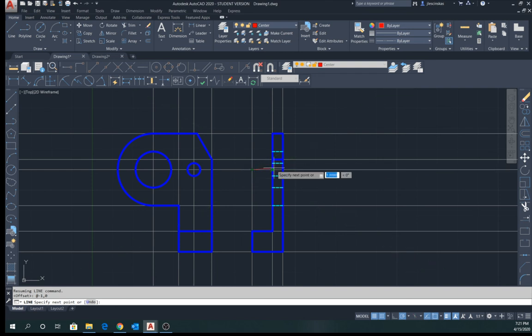And because I know that we're 1 inch away here, this is 0.5 inches wide, I should make this 2.5 inches long, and that will snap it exactly 1 inch from the other side. So that takes care of our center line. I haven't put in center marks yet, and I'm not going to do that yet. We'll do that when we do dimensioning.